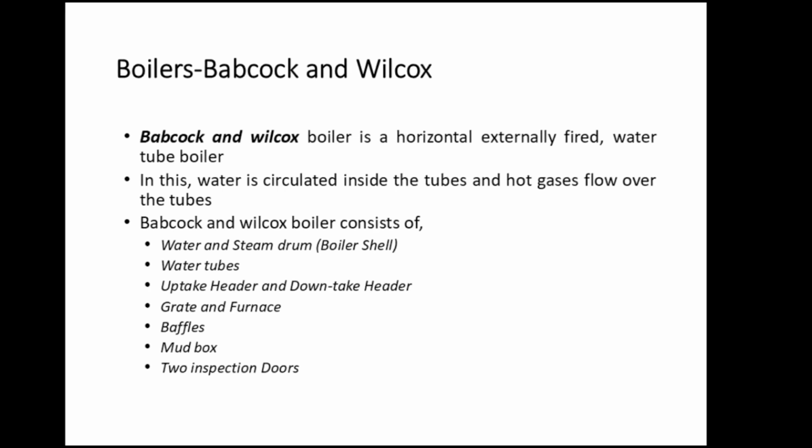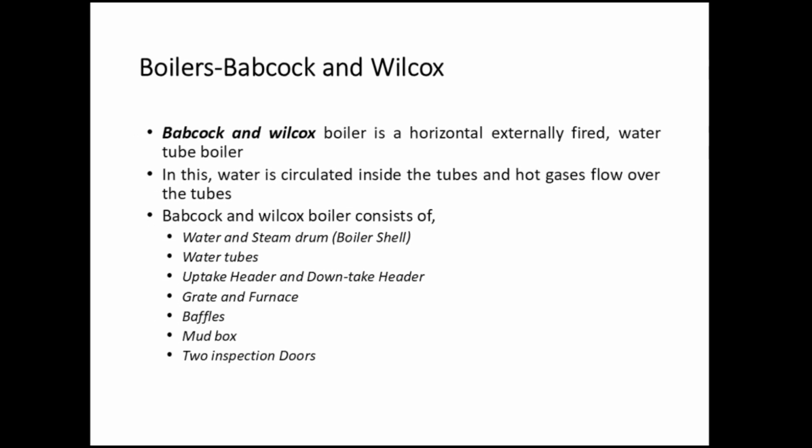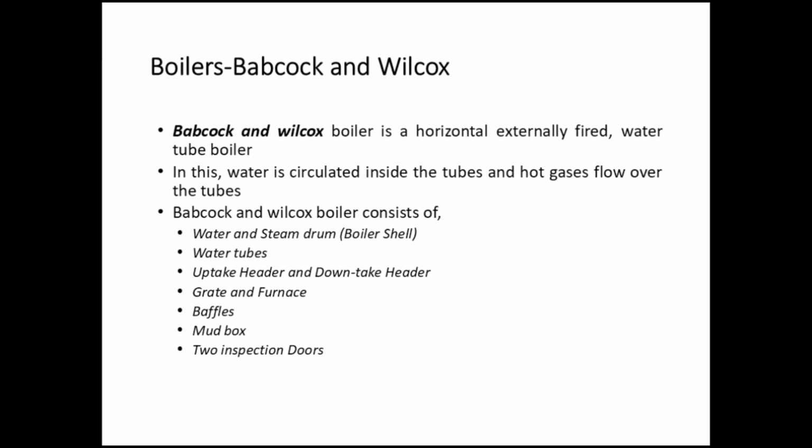Boilers. Babcock and Wilcox. The Babcock and Wilcox boiler is a horizontal externally fired water tube boiler. In this, water is circulated inside the tubes and hot gases flow over the tubes. The Babcock and Wilcox boiler consists of a water and steam drum boiler shell, water tubes, uptake header and downtake header, grate and furnace, baffles, mud box, and two inspection doors.